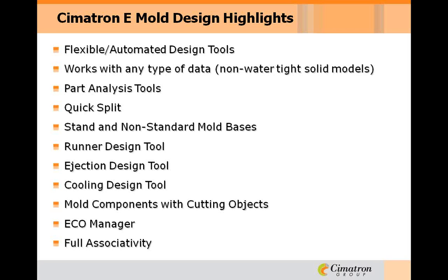The flexible, automated design tools, working with any data. Some of the part analysis tools, as you can see, was set up for mold making, where you get the 2D projected area, the quick split, the standard and non-standard mold bases, runner, ejection, and cooling design, mold components, again, with the cutting objects, the ECO manager, everybody gets engineering changes.